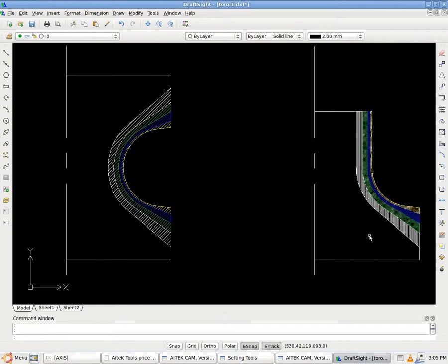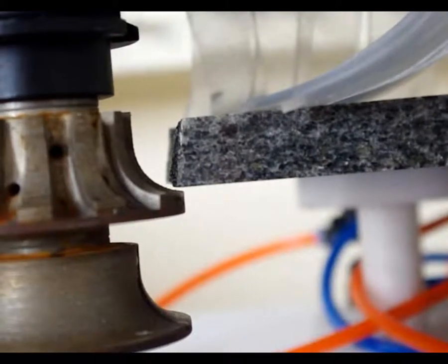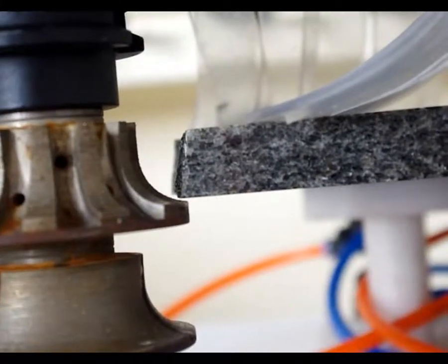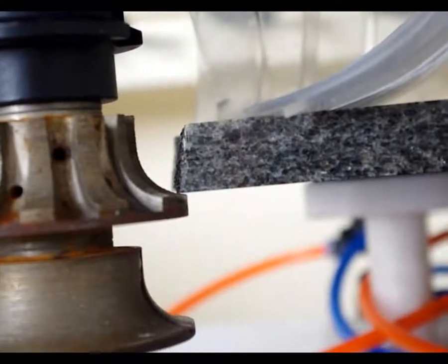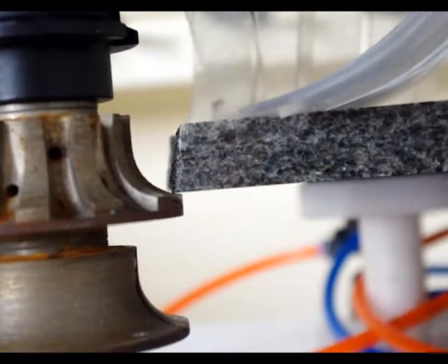For polishing wheels, you must first pass the diamond tools, and then set the polishing wheels touching the shape left by the diamond tools. Because it's easy for polishing wheels to change shape, you don't want to set them in the wrong position. I will show you the position of the first tool. This is where I will set my first tool.